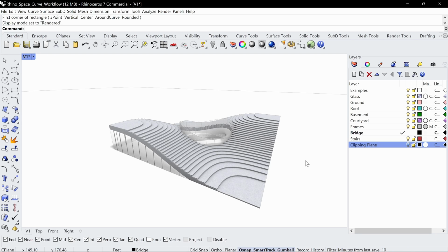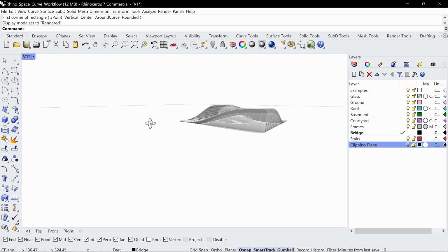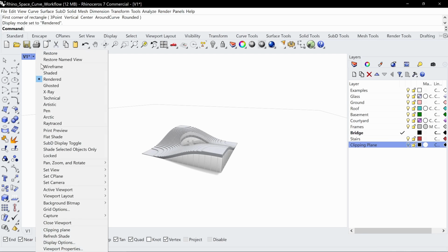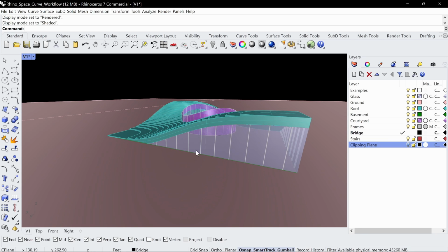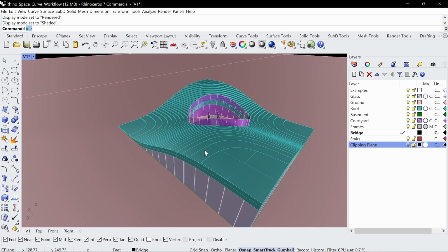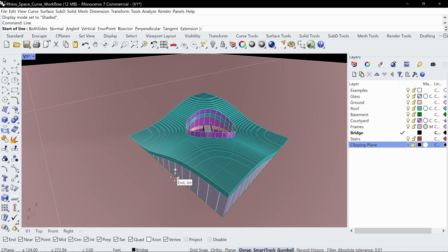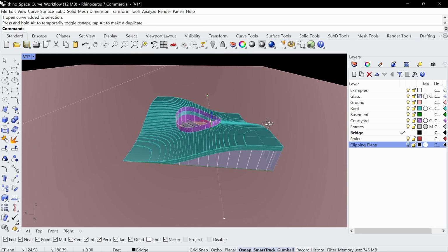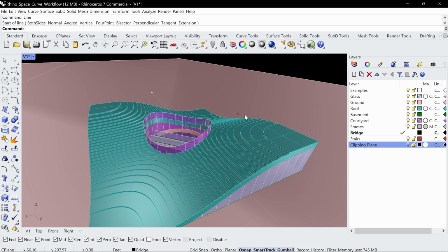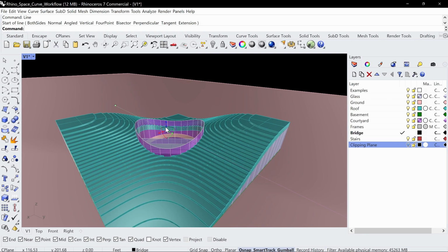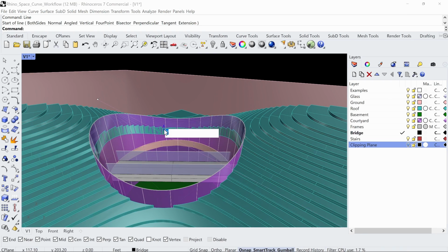So the first thing that I want to do is draw a regular line and establish a boundary of where I want the open to below to start. So I'll just draw a random line anywhere for now. Just go ahead and draw a random line across, right? And let me just move it here. And I'm going to extrude upward 8 feet. And I'll tell you why I'm using that distance. So let me just click on the solid blue dot up here and just do 8 feet, enter.